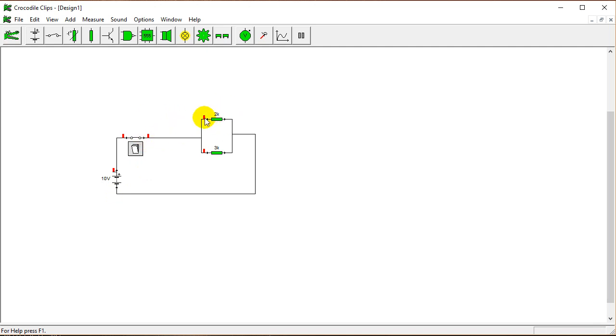As we were using a voltmeter in order to measure the volts, now we are going to use an ammeter in order to check the current that is flowing through this resistor and through this one. We can just place the cursor here and we see that the battery is giving out 8.33 milliamps, and if we place the cursor here, this one is getting 5 milliamps and this one is getting 3.33 milliamps. So the current that is being generated by the battery is divided between these two resistors. The one that has a lower value is getting more current than the one with the higher value.